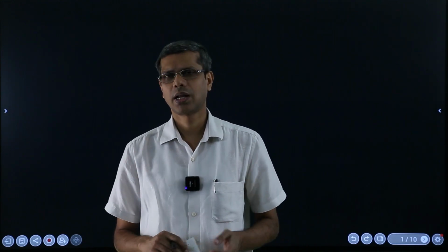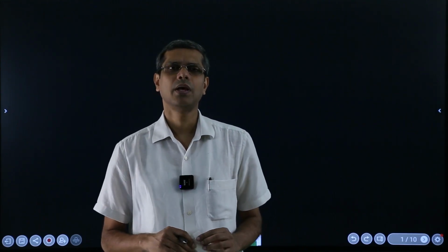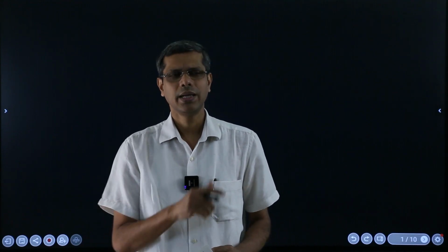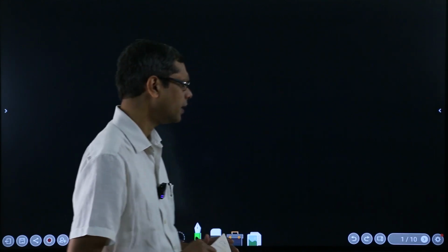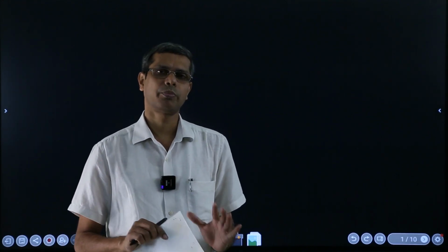In the last few segments, we were talking about the case of pure bending, and in that situation we discussed what the deformation and strain fields are, what the stresses are, and even in the previous segment we were talking about the radius of curvature. When a prismatic beam is under pure bending, it takes the shape of a circular arc, and we were discussing what its radius of curvature will be. Now, those were about pure bending.